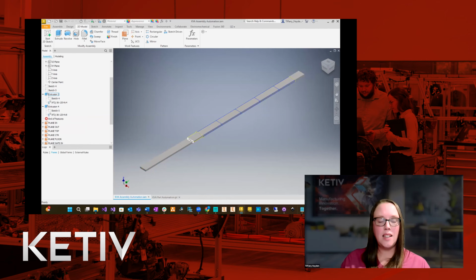Something that I put in on the idea boards for Autodesk Inventor, and I'm hopeful that it changes in the future: to be safe on extrusion cuts, if you're dealing with a pattern, you want to automatically add the first component of the pattern. In a lot of ways those aren't going to be cut away anyways, but it's a safeguard.